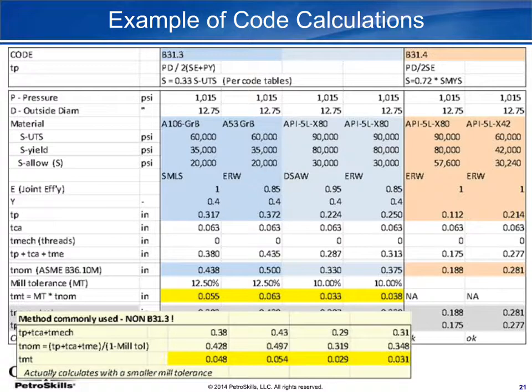So installation stress is a big issue that we need to think about. Maybe I should clarify what I'm thinking about when I talk about installation stress. Here is perhaps an offshore pipeline. When I'm lowering a pipeline to the sea floor, I have to put a lot of tension in that pipeline, and therefore stress on the pipe. The bending stress and tension stress on an offshore pipeline installation is commonly higher than the actual operating stress. And that's what I mean by installation stress.